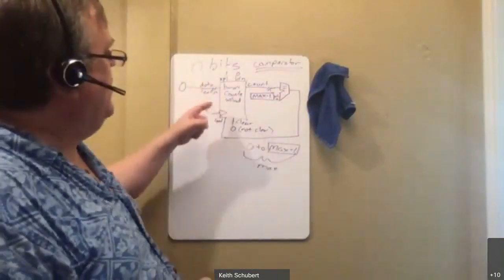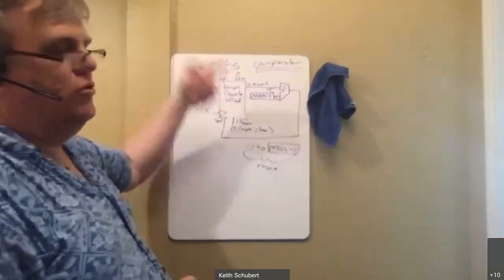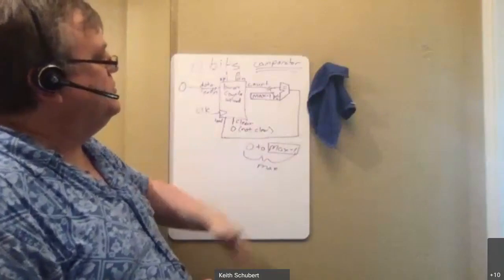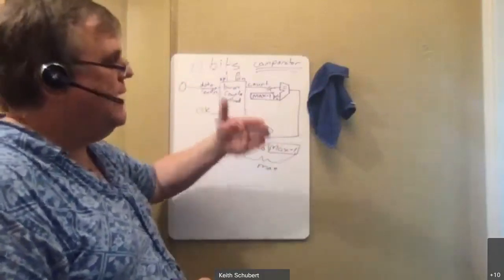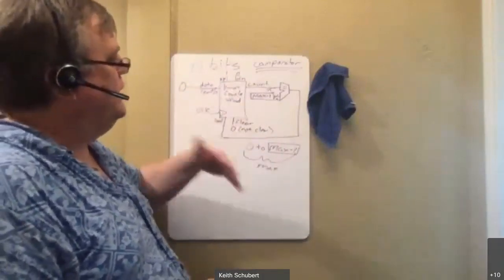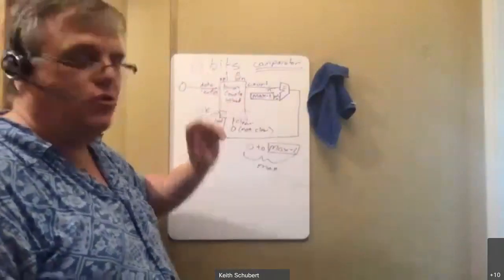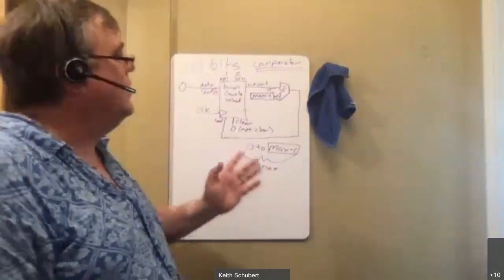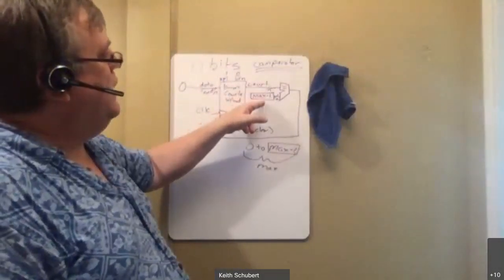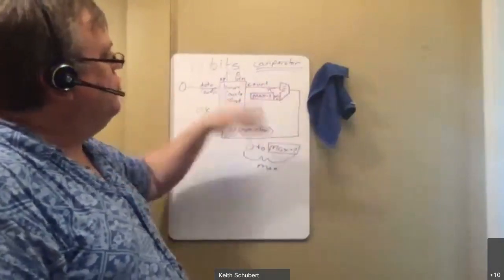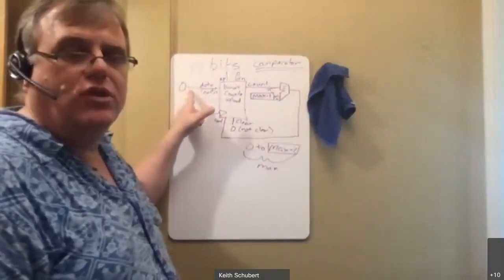So that means it's going to count 0, 1, 2, 3, 4, 5, 6. It'll get all the way up to max minus 4, max minus 3, max minus 2, max minus 1. Each time, it's going to just normally count. That's all built into the regular binary counter we did last time. The second the output is the same as max minus 1, we'll just tell it, okay, don't go to the next number, just load this new number in for me.